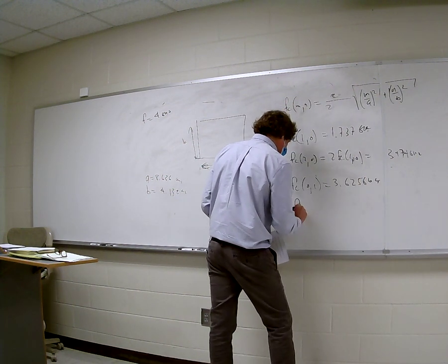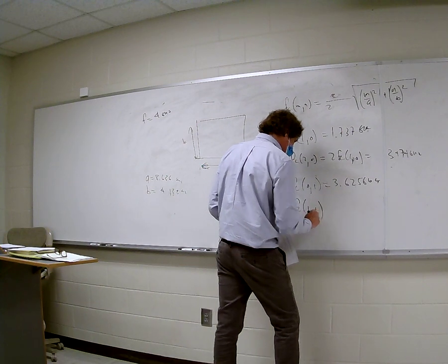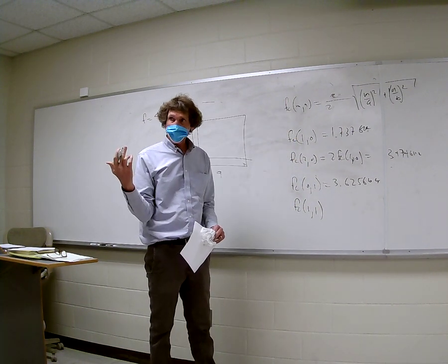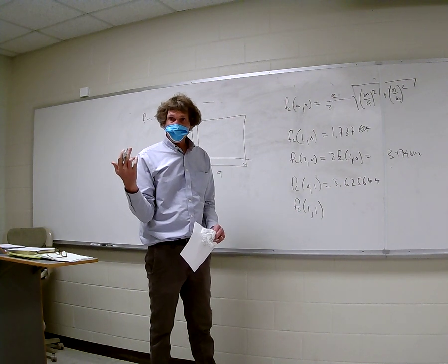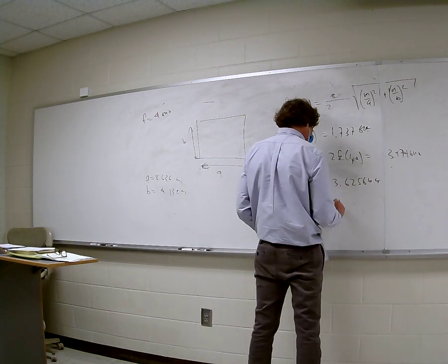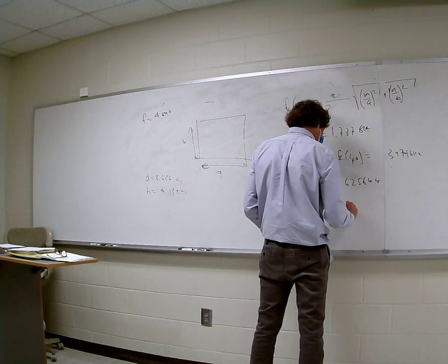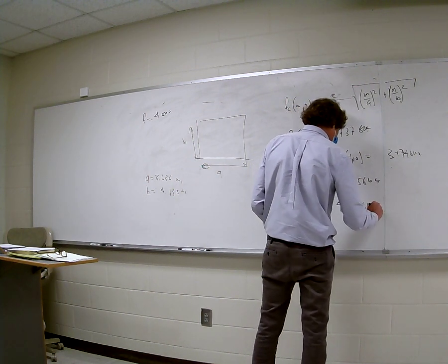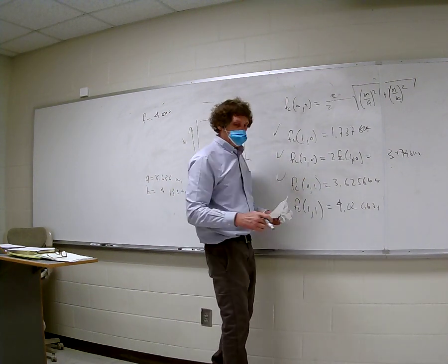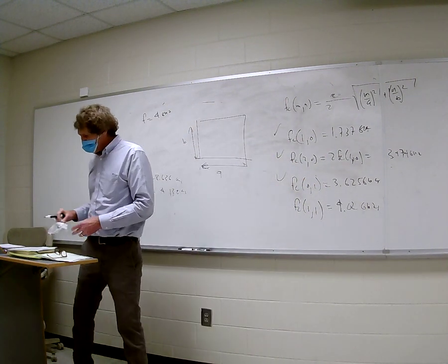And finally, FC11, which is the first TM mode, because TM have to have a 1 and a 1, both for M and N, or else the sine function goes to 0. So you want to tell me that one? It's 4.02 gigahertz. Right. Which means only this one and this one propagate. That's it.